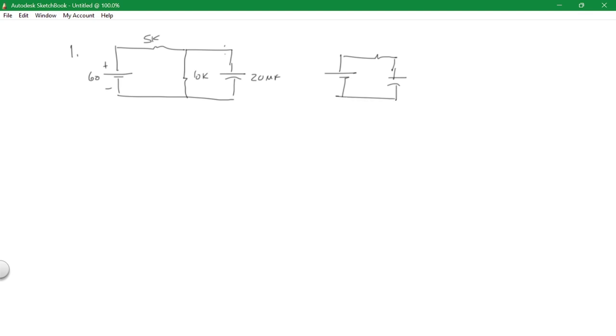So you got to Thevenize. You got to cut the circuit and then ask what the voltage is. What is this voltage right here? What is this resistance right here? And then you can do it. So if you cut the circuit right here and you ask the question, what would be the voltage across the 10K? Well, V Thevenin is equal to 10 over 10 plus 5, which is a voltage divider, times 60, or 2/3 of 60, or 40. So you come over here and you write 40.